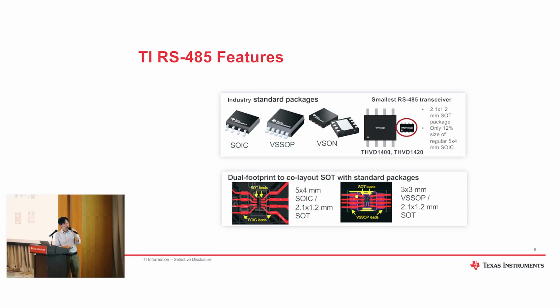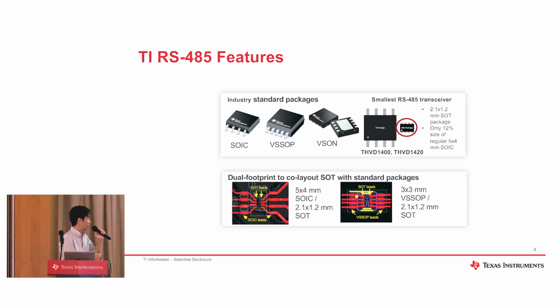This is one recommendation to do the dual footprint co-layout for the SOT with other standard packages like SOIC or VSSOP. You can see that the pinout makes it easy and convenient to do the co-layout, and this helps you to have more than one package option on one PCB. So in case you need the smaller one, you can use the SOT package.